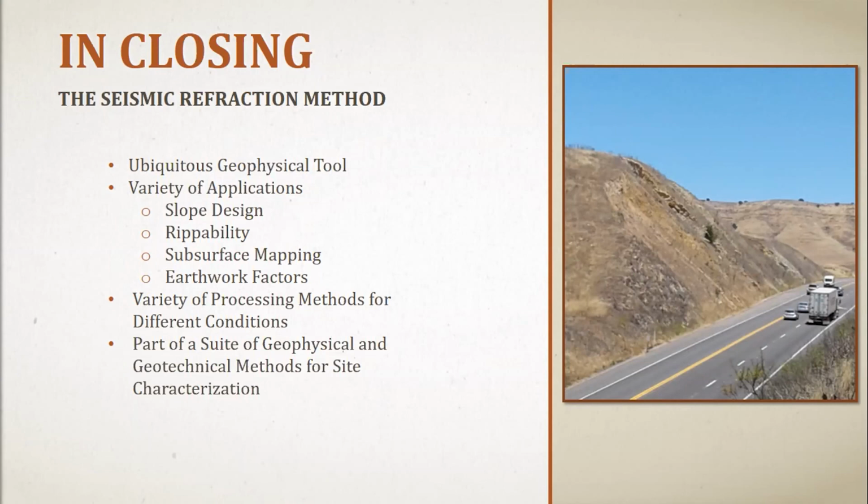So although valuable data can be gathered from a standalone seismic refraction survey, seismic refraction is best used as part of a whole investigation process that can include other geophysical methods such as electrical and electromagnetic techniques, as well as geophysical logging such as PS suspension logging, optical and acoustic televiewer, and e-logging. Of course, this process also includes geotechnical borehole logging, geologic mapping, and regional geology review. So in short, geophysical investigations are an important part of the site investigation process that should be utilized where feasible for better planning and design.